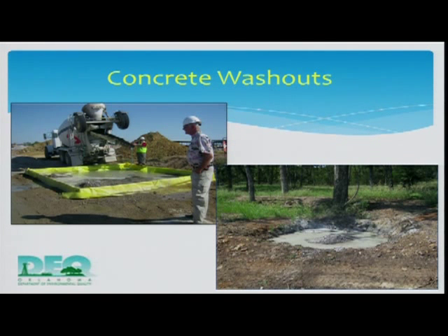There are a number of different commercially available concrete washout facilities, but a simple pit dug to hold that material until you have time to clean it out works too. It may need to be cleaned out more often during certain periods, like when you're pouring curb and foundations or whatever may be going on. But at other times, it may not be used hardly at all. Be aware that it does need to be signed properly, and the guys need to know where it is so that they can go use it.